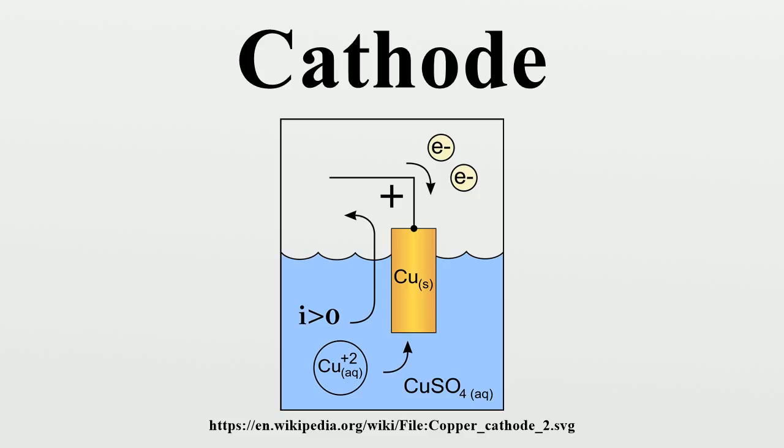When p and n-doped layers are created adjacent to each other, diffusion ensures that electrons flow from high to low density areas, that is, from the n to the p side. They leave behind the fixed positively charged dopants near the junction. Similarly, holes diffuse from p to n, leaving behind fixed negative ionized dopants near the junction. These layers of fixed positive and negative charges are collectively known as the depletion layer because they are depleted of free electrons and holes.